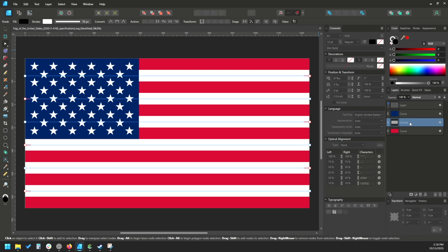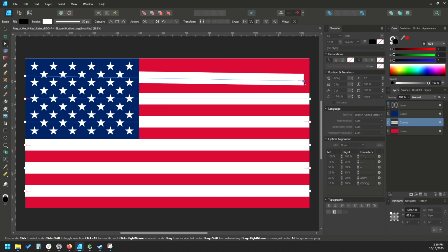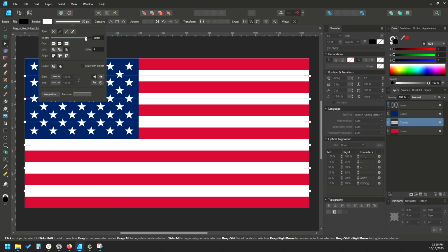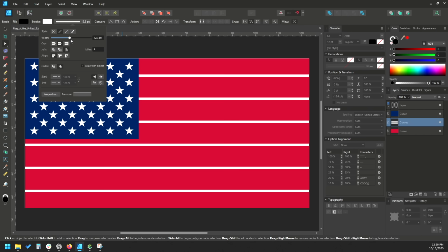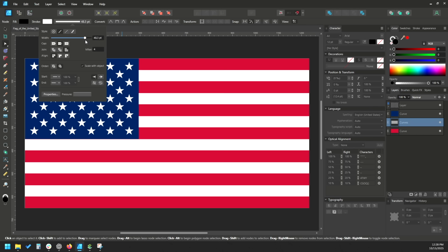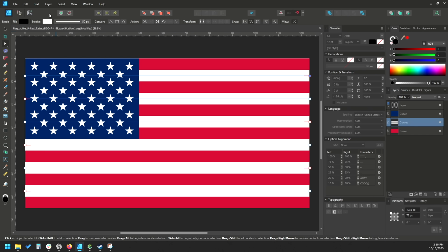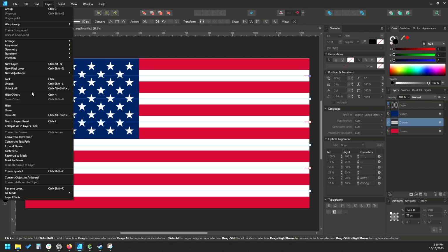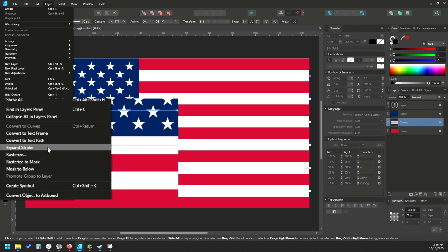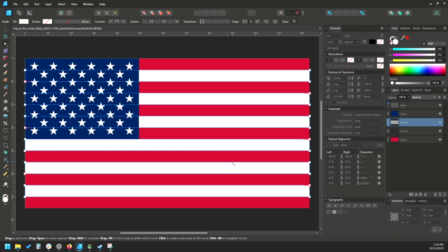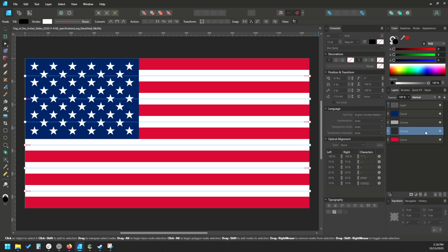That's because in a browser, those lines are drawn with an exaggerated width, also known as stroke. Visually, it looks correct, but it doesn't actually bound an area. There's not enough information to create a toolpath from this feature. To permanently force that stroke representation of the stripes into rectangles, I'm going to use a function in Affinity Designer called expand stroke. Might be called something else if you're using another program.